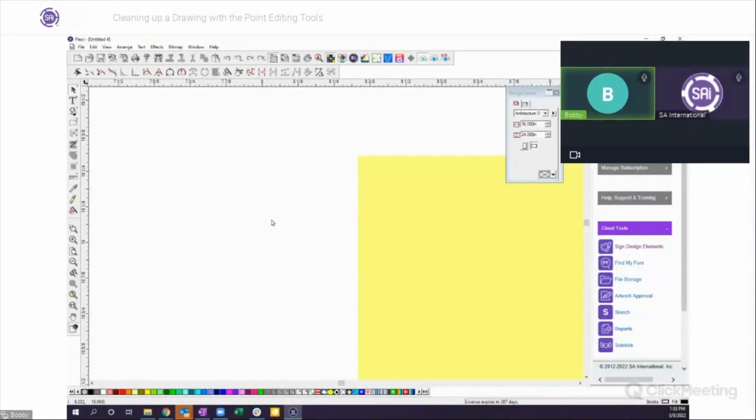So if you want the stroke line to be black, that's what it is. It's not really there. It shouldn't print. If you went to print it, and if visually it bothers you, then yes, you can get rid of it by holding the control key down as you drag your cursor onto it, and you notice it becomes a pencil when it's on there. When I let go, now my stroke line is pink.